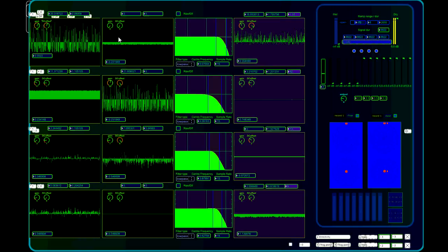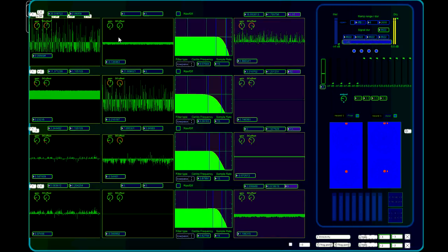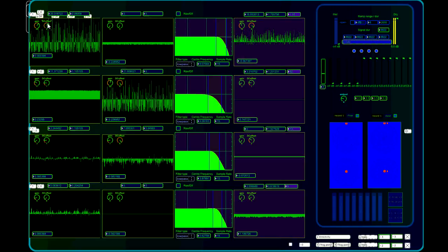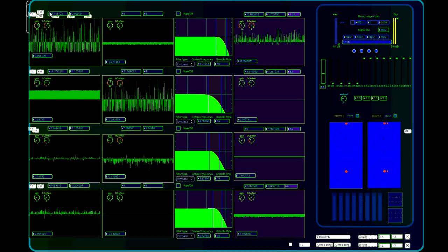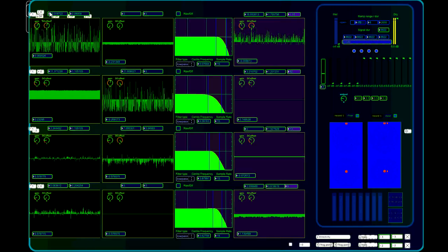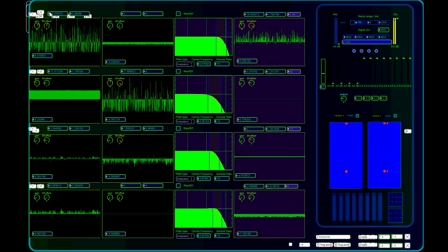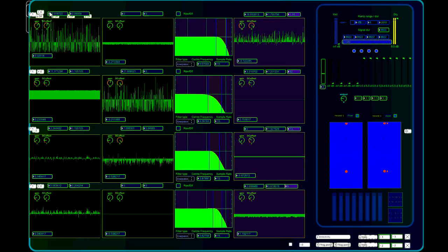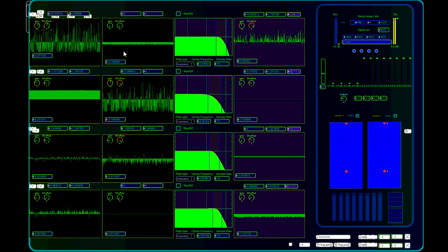You put a signal going one way, and you put the same signal coming back the other way, but without the signal you want on it. So the only thing the cable coming back will have on it is the noise. So when you invert those two signals together, the noise cancels itself out. That's phase cancellation, and it just leaves you with the pure signal. Exactly the same way an XLR cable works in audio, but this is another way you can clean up signals